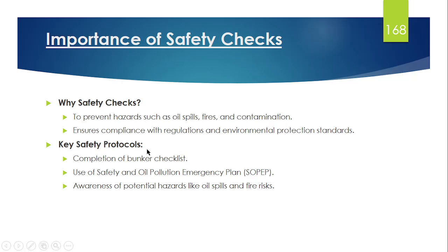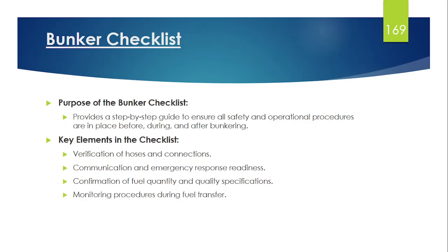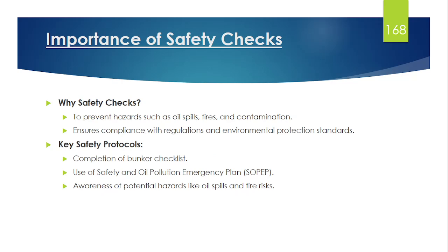We have to complete the bunker checklist. After that, we have to arrange SOPEP equipment, and third, we have to be aware of the potential hazards which can take place, like oil spill and fire risks. So basically, what I mean to say is that we go one by one. What is the bunker checklist?